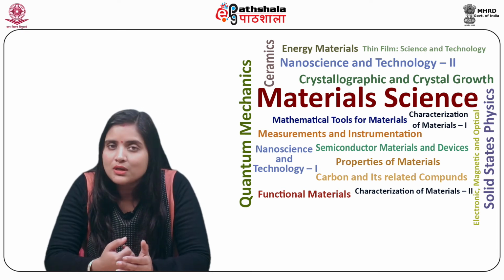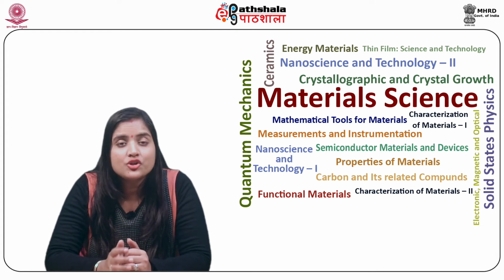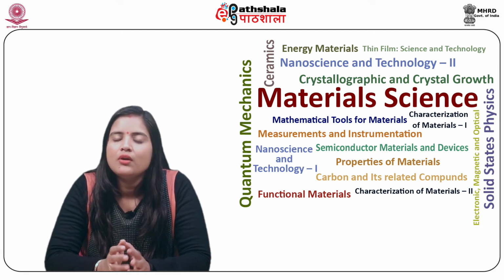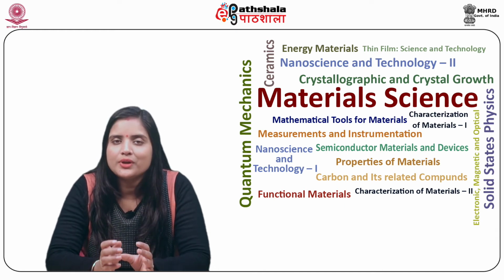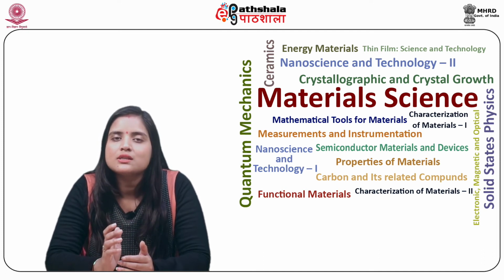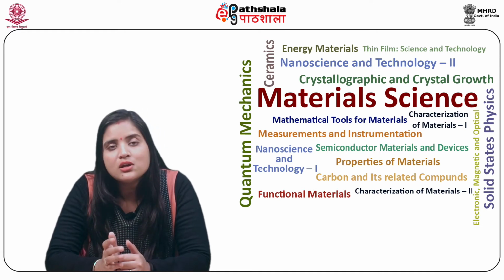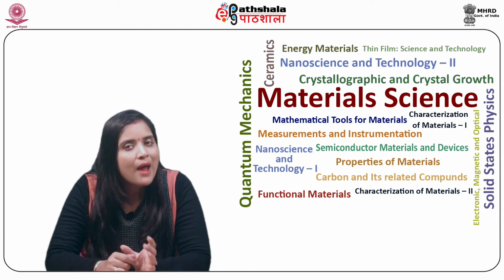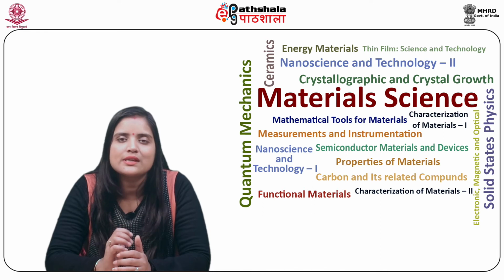Alloys can be prepared by using different equipment such as attritor, planetary mill, or horizontal ball mill. The working principle for all these techniques is the same. During alloy formation using ball mill, two processes simultaneously occur. One is the fracturing and the other is the cold welding of powders. Thus, it becomes imperative to create a balance between these processes for successful alloying.